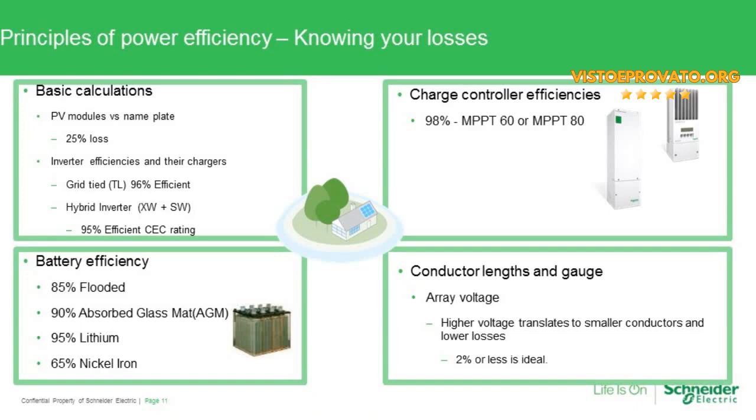So understanding your power efficiency and understanding the losses that occur within a system is really where the rubber hits the road for proper sizing. And oftentimes, if you miss one thing, then overall the system is at risk of harm, because either wire sizing isn't correct, or the amount of solar put on site isn't going to meet the needs of the customer, or the battery bank isn't large enough and doesn't meet the needs for a return on investment from the system, either it being a grid-tied battery-based system where it's just a backup system, or AC coupling where again it's just a backup system, or with the potential of doing some self-consumption on site.